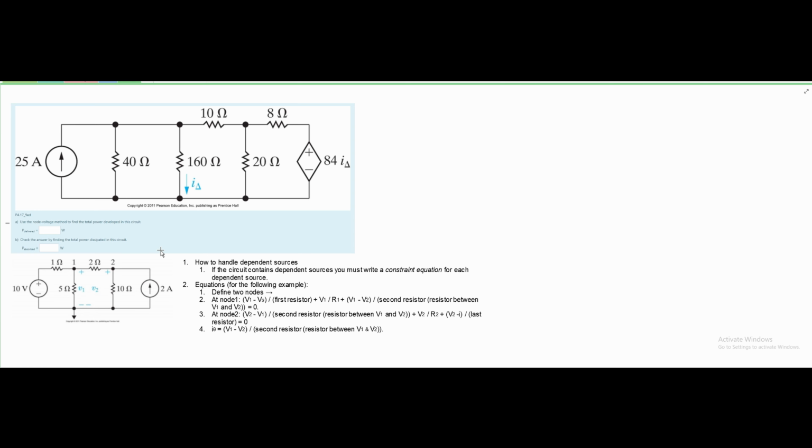So the total power that's going to be delivered is found by using the power formula, and this is voltage times current. So we have our current right here, and we know that our voltage is going to be the same over this resistor and this resistor, since they are exactly in parallel with each other. That means we have to find the voltage. To find the voltage for one of these, we would just do a plus minus and then have our V1 here. This will find our voltage, and then we could multiply it by our current and get the power delivered by this current right here.